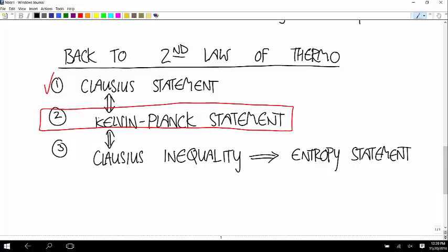And one of the uses of the Kelvin-Planck statement is coming up with not just definitions of performance of these cycles, that doesn't depend on the Kelvin-Planck statement, but coming up with, for the conditions that you have, really it's for the temperatures of the two reservoirs that you have for your cycle, limits on the performance of the cycle.